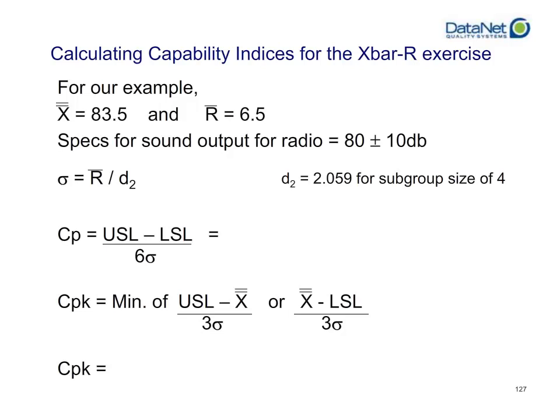We're going to use CPK, which is the minimum of the upper spec minus the grand average over 3 sigma, or the grand average minus the lower spec limit over 3 sigma. We're going to take the minimum value of those two to calculate our CPK. And then we're going to determine what this means for our process, how capable our process actually is.